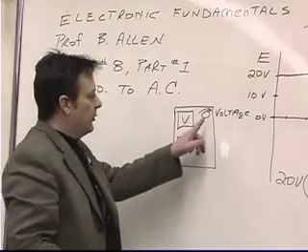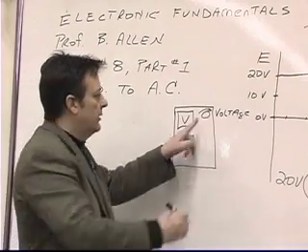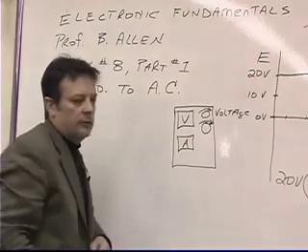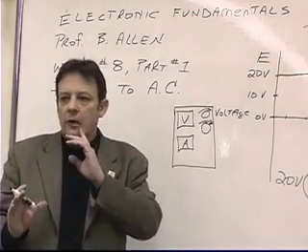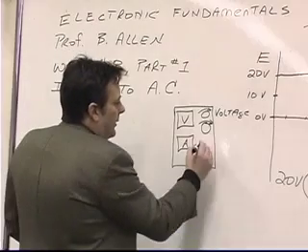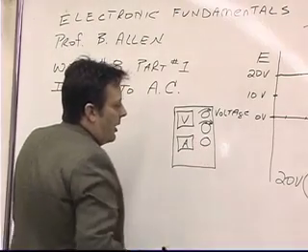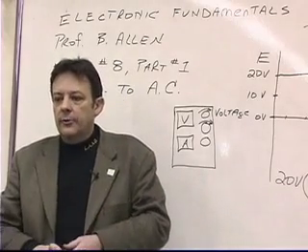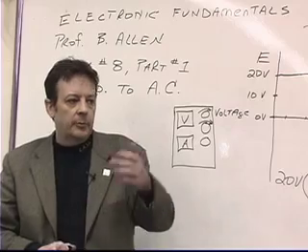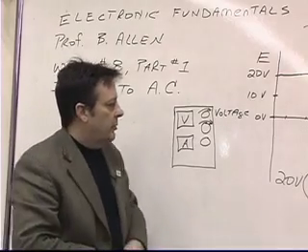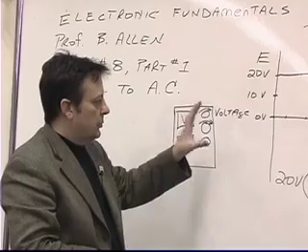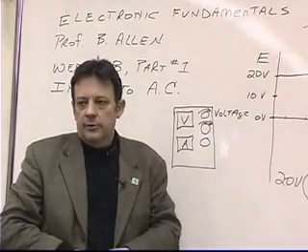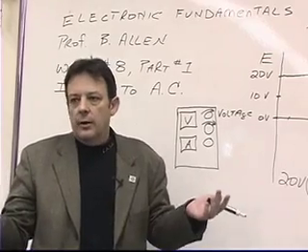This is the coarse setting on the voltage, and then the next knob down is the fine setting on the voltage so that we can get it dialed into a really accurate number. And then the third knob down is a knob that we can use to set the maximum current that the regulated DC power supply will produce. But for the purpose of this explanation, we're not going to worry about the current setting. We're just going to say that it's set to generate an amp.